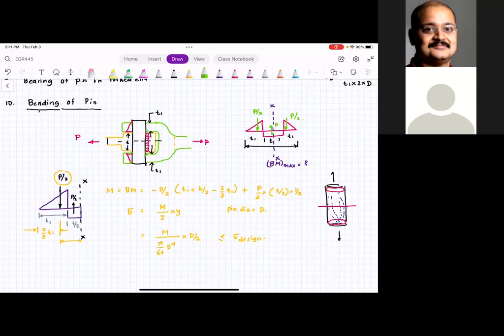That is the reason why you would notice the pin and the inner surfaces have a surface finish requirement. Why surface finish requirement? Because the amount of pitting will be reduced if you have a smooth surface. Rather than having a rough surface, which will give rise to more localized stresses. If the surface is smooth, then the localized stresses would be minimized.